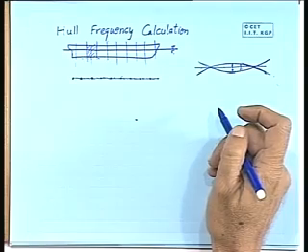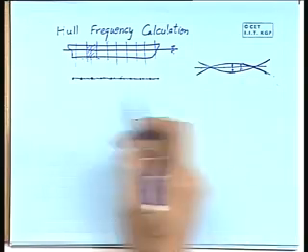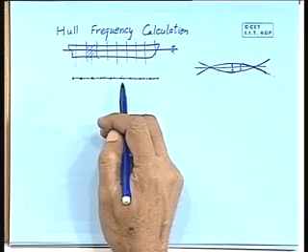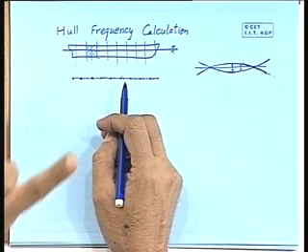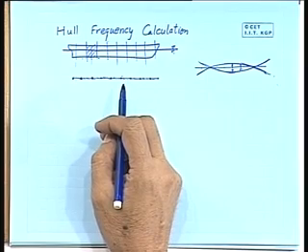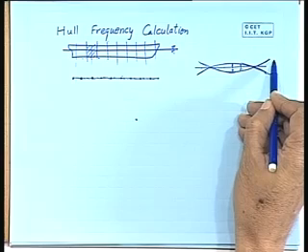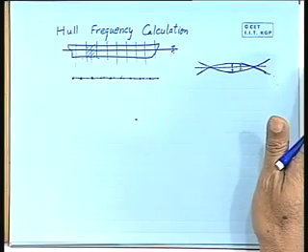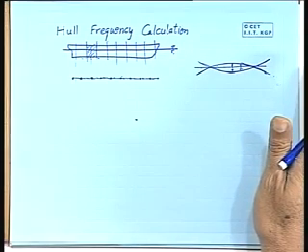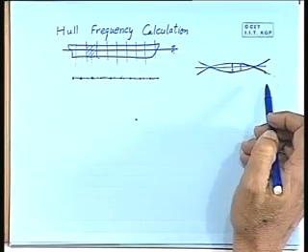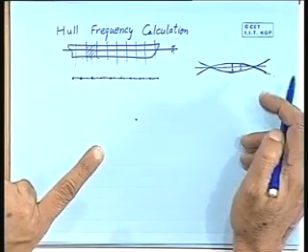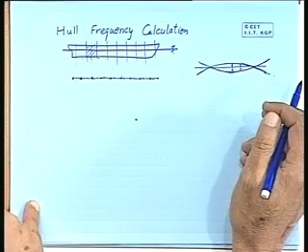Okay. So this dynamic displacement will give you some sort of dynamic acceleration, and that is a time dependent function, and from there you can find out what is the frequency. I am starting with some sort of a deflection pattern, and I am arriving at a deflection. Now the starting deflection pattern, if it matches with the derived deflection pattern, that means what I assumed earlier, that the ship is moving in this shape, is the correct shape.